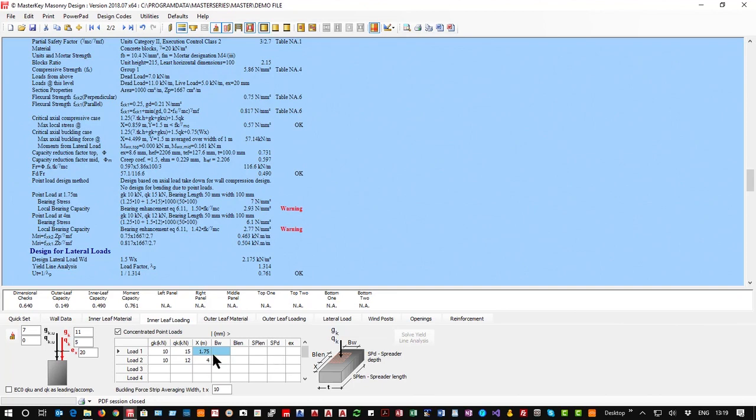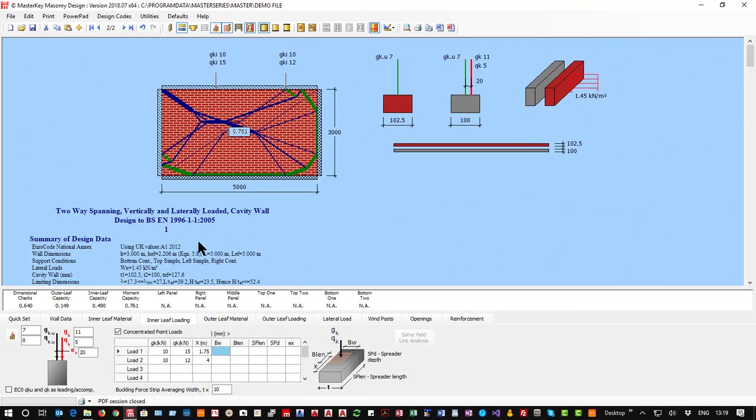Well, what we do is we put in some sort of padstone and we think about it. So this padstone, well, first of all, we would probably say, no, the point load isn't over a minute point, but is over a length and a depth into the wall. So it's going to be spread over 100 by 100 millimeters. So these now are all millimeter dimensions.